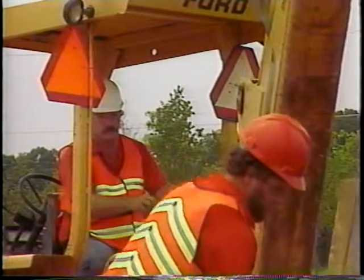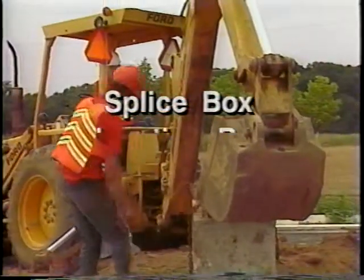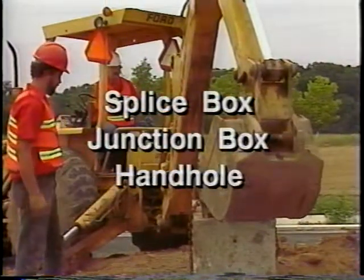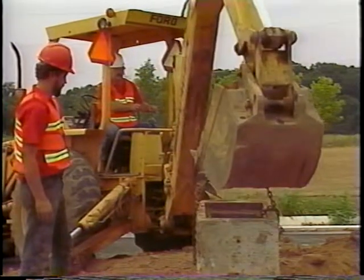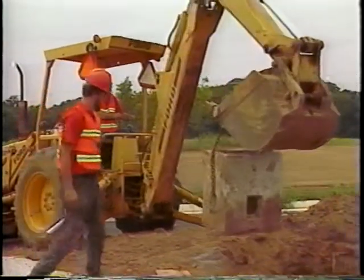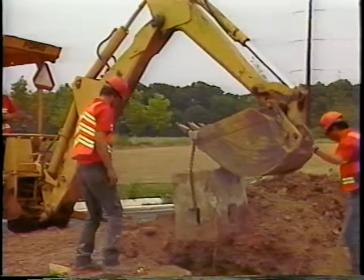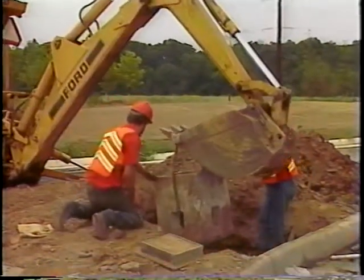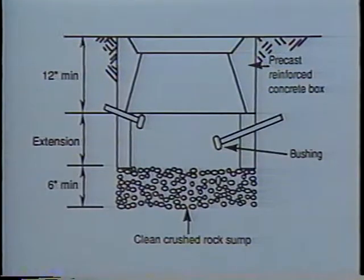The next step is the installation of the pull box, also called the splice box, the junction box, and the hand hole. The pull box houses the splices between the lead-in wires from the loops and the shielded lead-in cable to the controller cabinet. Made of concrete, plastic, metal, or fiberglass, these pull boxes are also required at intervals in especially long runs of wire. It is essential to provide all pull boxes with adequate drainage when installed.